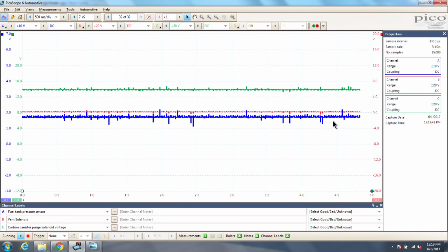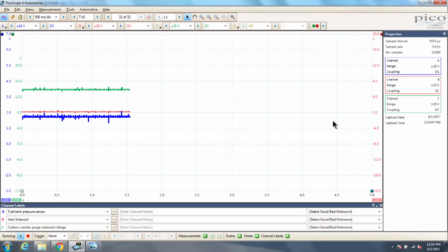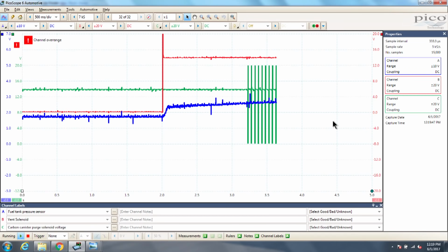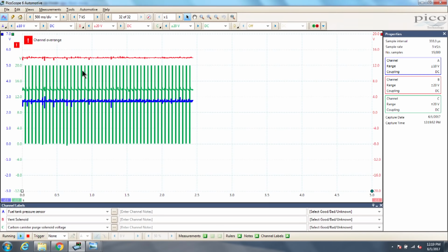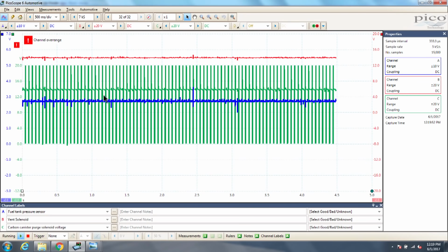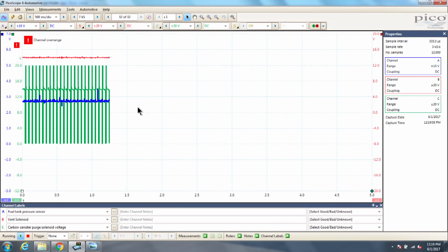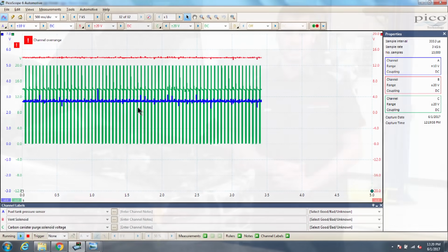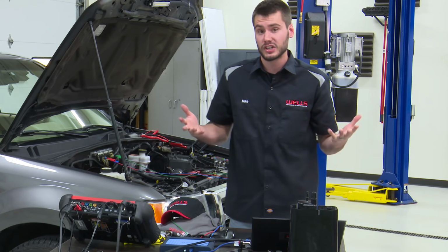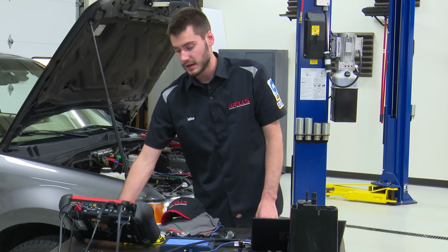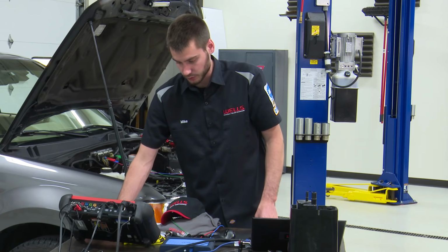And then if I go ahead and turn our vent off, there we go, I just turned it off, and look at our pressure return, and the computer said, I want to purge right away and turn the purge solenoid right back on. So sometimes you can do this with a scan tool. GM's pretty good with the evap purge seal test, but sometimes you can't, and obviously I can't even view the information I want to view with the scan tool.